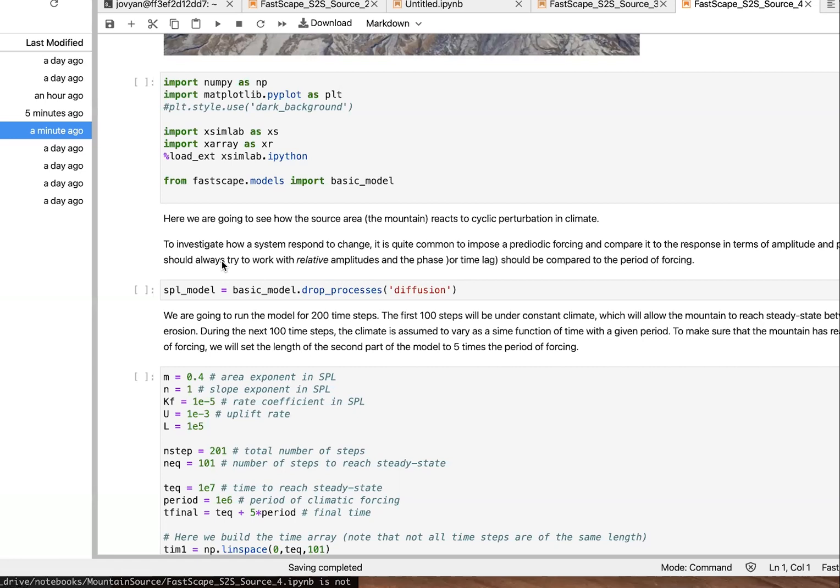And the other very important thing is the time lag. If I go up in the input, is the output going up and down at the same time? Or is there a phase shift between the two? They could be totally out of phase. They could be slightly delayed. Rarely in advance. It's very difficult for a physical system to produce a signal that actually is predicting the input, so we're not going to consider that.